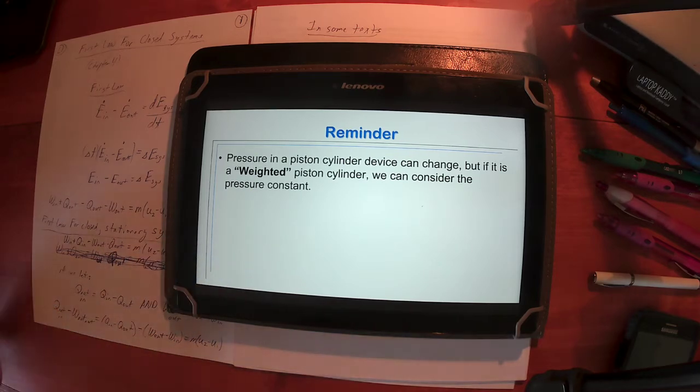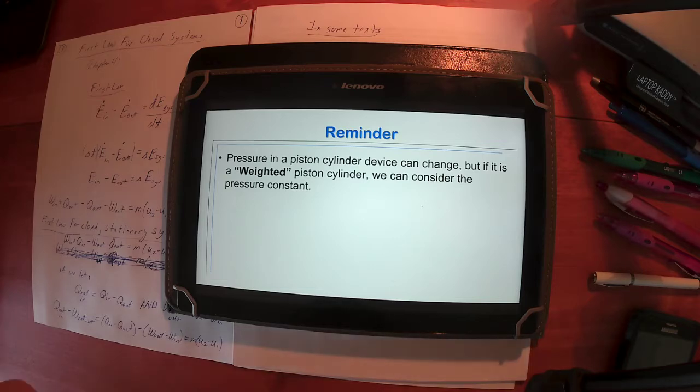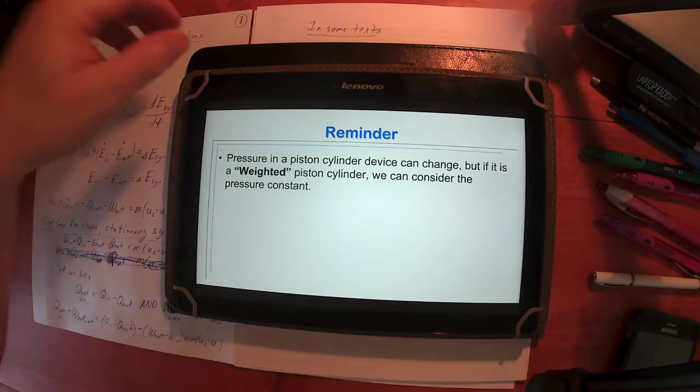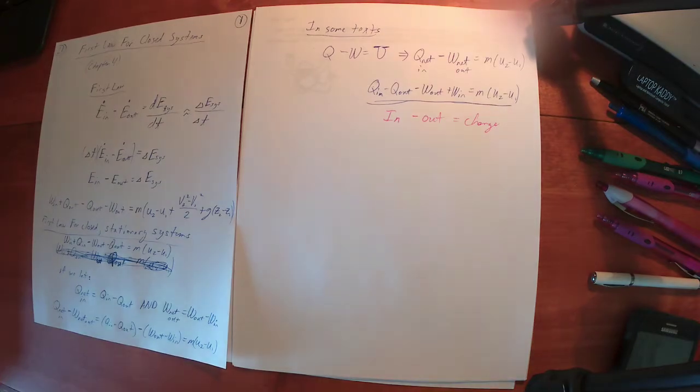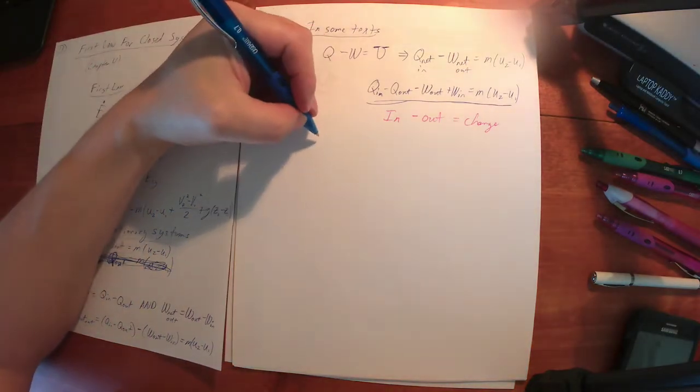They're telling you that a constant force or constant weight has been added to the lid of that piston, and so it's going to apply a constant force to that lid spread out across the area of that piston face, and that causes a constant pressure to be applied to the contents within, which is our system. If they do not tell you, at least in our text, I've seen some texts where any time you have a piston, you're supposed to assume it's constant pressure. That is not the case.